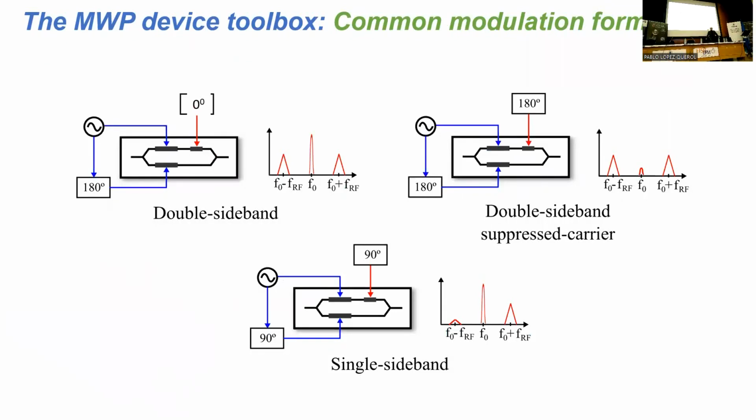Finally, regarding the transmitter, I will show you different ways in which we can operate the modulator. The modulator usually has two electrodes where we feed the RF signal, and we have another separate terminal where we do the biasing. That's the DC voltage. And depending on the configuration and the phase shift that we apply to the modulator, we can get different operation regimes.